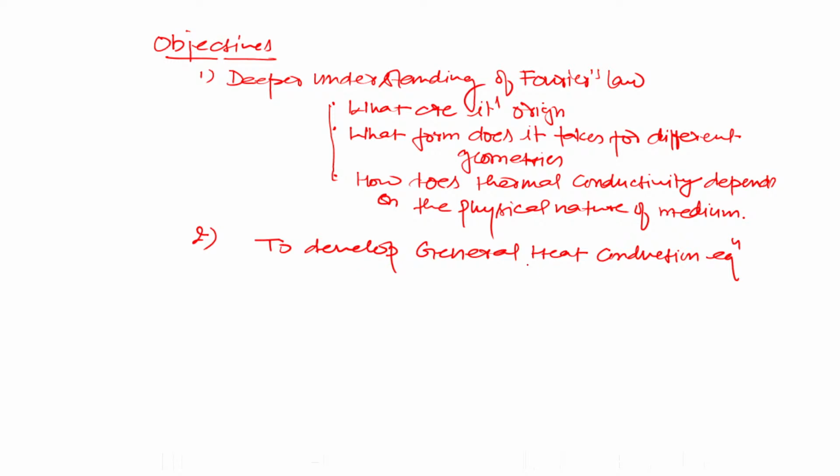See, once I get the heat conduction equation, through this equation we are able to find out the temperature distribution in the medium in which conduction is the only mode of heat transfer. And the solution of this equation will give the knowledge of temperature distribution. And once I know the temperature distribution, then I can find out the flux by using which law?